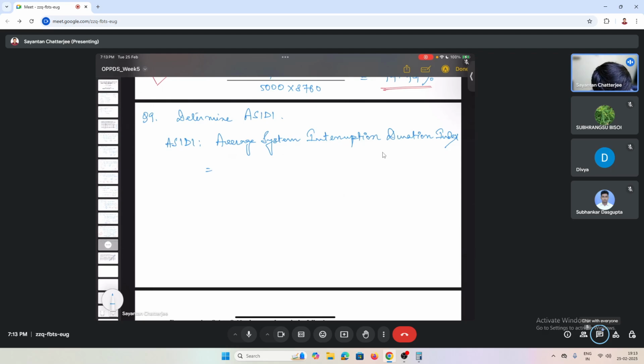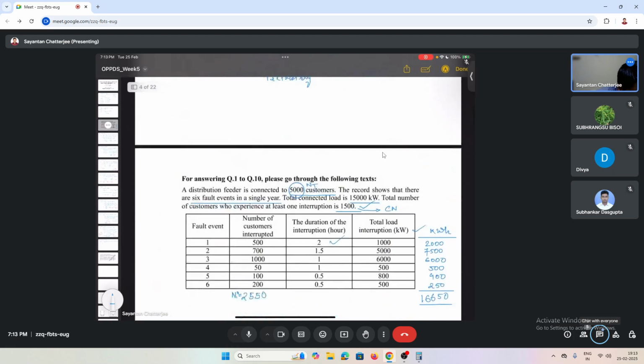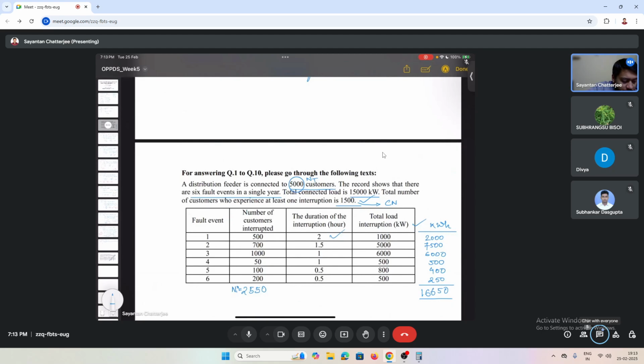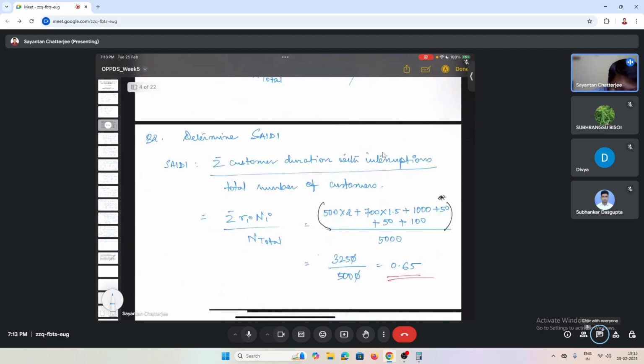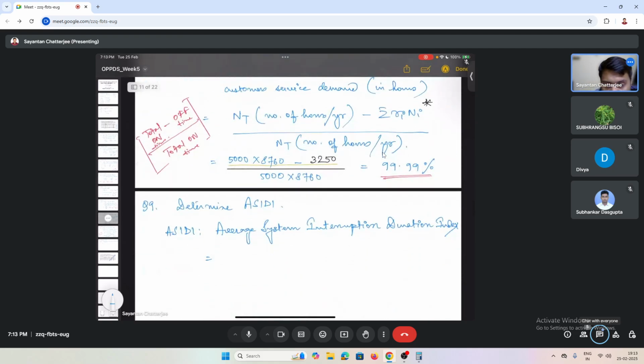since we have the total load connected, and since we don't have the information of the power factor given, for these cases we can consider the power factor to be 1. So with no information of the power factor given, we can continue using the kilowatt value as the kVA value, assuming that the power factor is 1. If nothing is given, definitely go for the power factor 1 value itself.